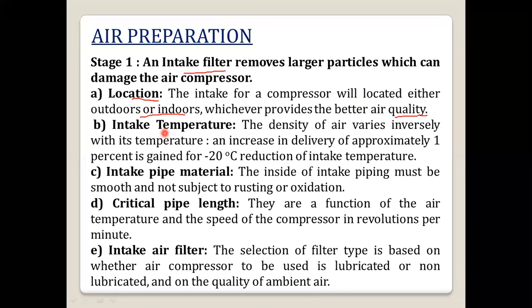Then we have to see the intake temperature, because the density of air varies inversely proportional with its temperature. An increase in delivery of approximately 1% is gained for every 20 degrees Celsius reduction of intake temperature. So again, we should not keep the compressor where the temperature is very high. The intake temperature also matters for the generation of the compressed air.